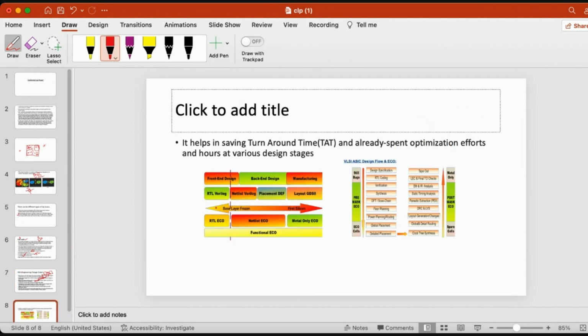So this is one thing. If you see, this is functional ECO and this is metal ECO. You will not understand this now. Don't memorize this by heart. Simply I captured it. Generally ECOs are of two types: timing ECOs and functional ECOs. In timing ECOs, we can add a cell. In functional ECO, we have to play with the metals. So suppose there is a necessity to add a cell, then what do you do? We have programmable filler cells. These were placed during your layout. Once your design is freezed, there are empty spaces in your design.